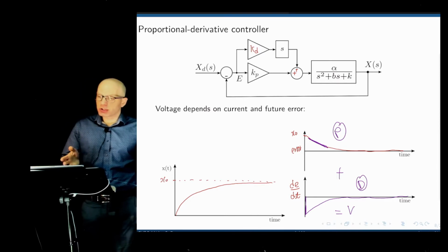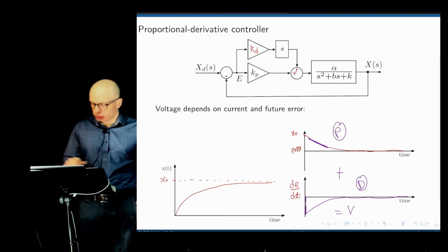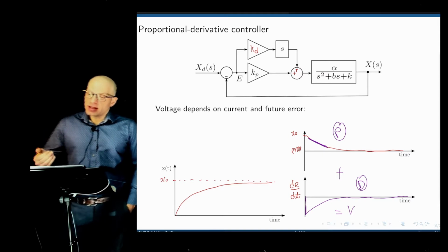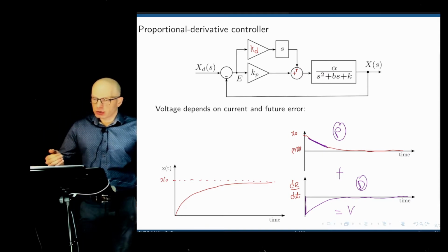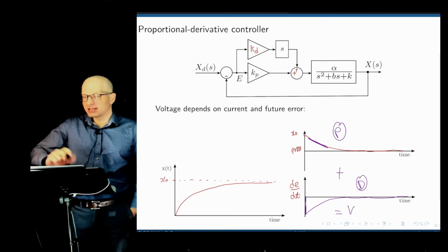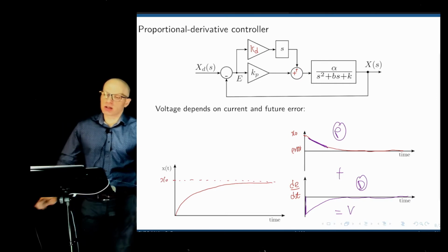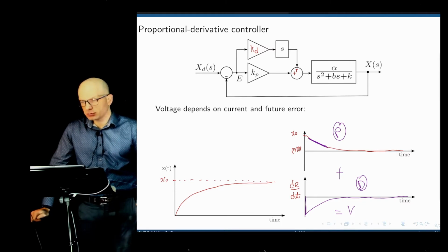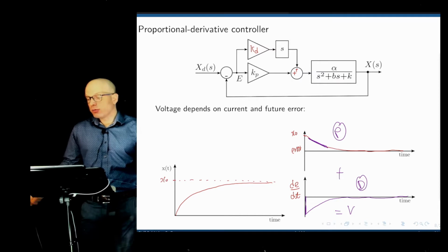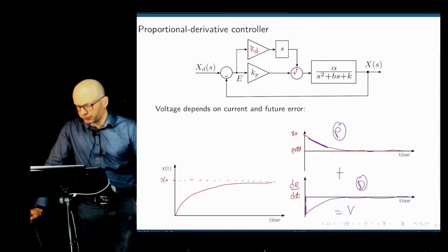So in this particular case, if you only had the proportional controller for this curve here, we would apply more energy to the system than if we had a proportional derivative controller, because as the error decreases, we have a negative gain. Negative gain takes some of that control action out and compensates for the fact that we're moving towards the destination. And hopefully that decreases the overshoot.